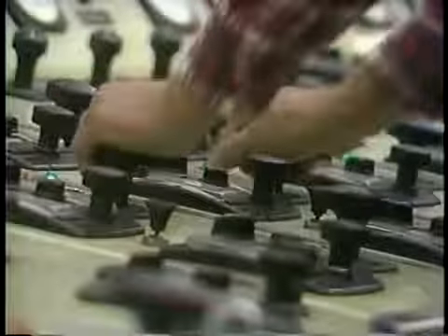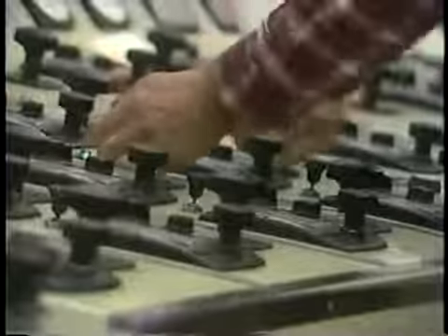Since tube ruptures usually occur without warning, an operator must be constantly ready to shut off all fuel flow to the burners and purge the boiler of combustibles. Since a tube rupture can cause a loss of flame, an operator needs to know how to verify that there is a boiler flame. Let's go on to look at the indication that an operator uses to verify a loss of flame.